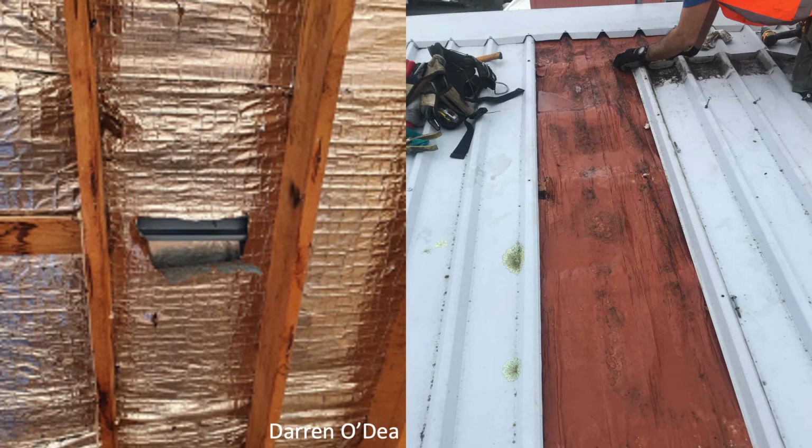We also have an example there from New Zealand, where we've got craft paper that has exceeded the ability to absorb the moisture that has accumulated on the underside of the roofing iron, and that's led to ponding. So we've got so much moisture there that we've actually got little puddles forming, and that's pushing down on the membrane. Any perforations, and you can see that there are some there, are going to obviously be a problem, because that water is going to find its way into the building below.